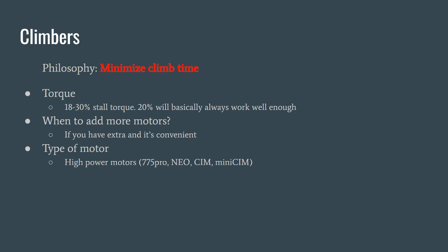That's just a lot of gears, and there's no gearbox I can buy that has a 20-to-1 reduction that carries that much power. But if I add another motor, how much torque do I have with 2 motors? Yeah, that's right. And now I only need a 10-to-1 reduction, and that might be easier to buy.